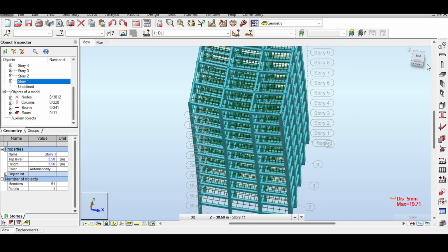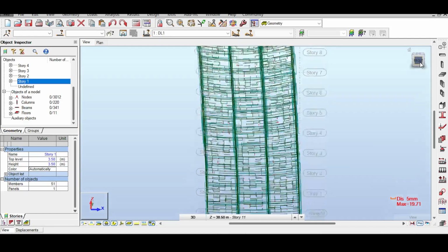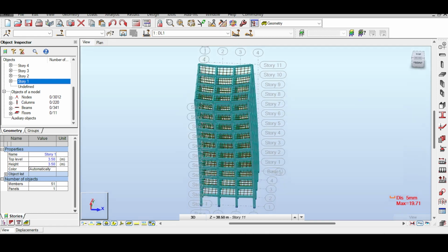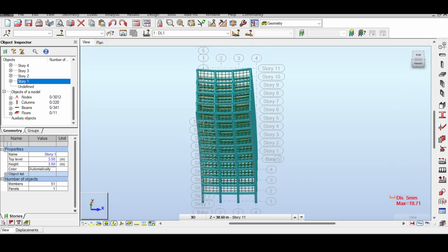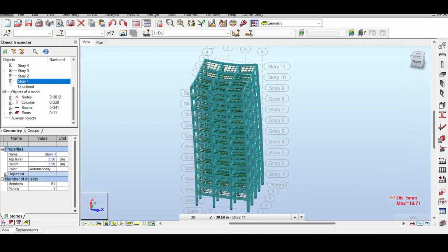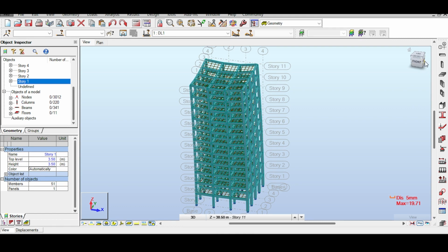So okay, that's basically a quick rundown of the twisting and turning of a structure from vertical loads, why it happens, and how we could basically modify it to not happen. The modification is not easy because you need to have double symmetric, which is very hard to achieve. And this is something I want to finish my video with, because next time we'll be working on our big tower to try make it as less twisty as possible. Spoiler, it's impossible to achieve 100%, but, well, we try our best.